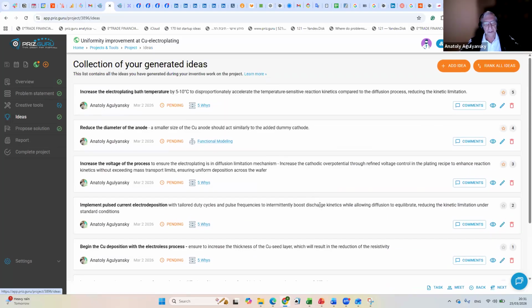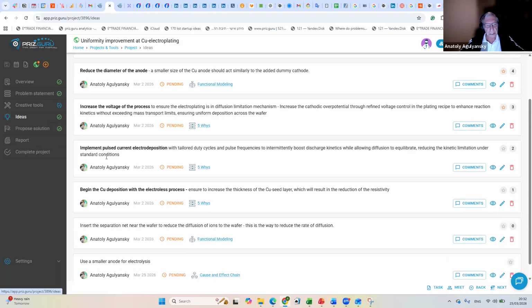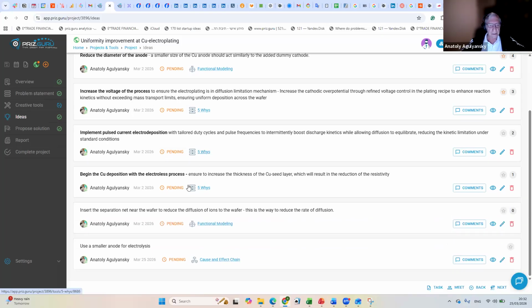The ideas: first, increase temperature. When we increase temperature, we make the interaction faster. Reduce diameter of anode, which is what we talked about. Increase voltage of the process. Implement pulse current, pulse and reverse current.